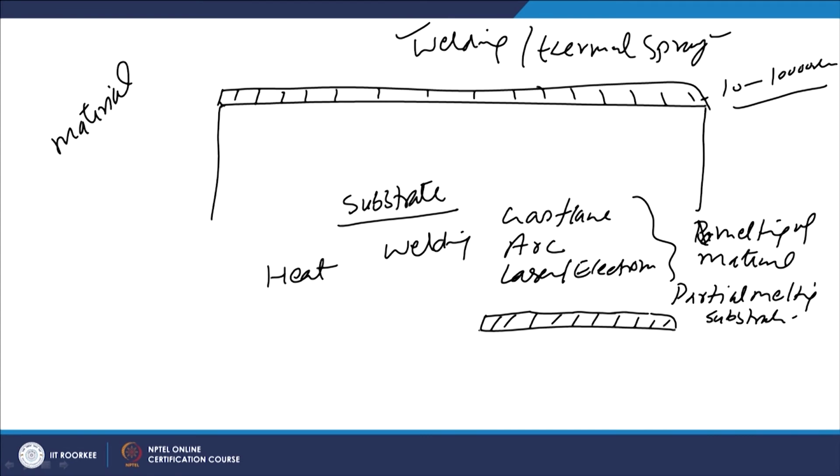At the same time, a little melting of the base metal is also required, so that a good metallurgical bond between the applied material and the substrate can be realized. When the melting is achieved, we have molten metal of the material to be applied as well as molten metal of the substrate material, and intermixing leads to the development of a layer of the required properties.